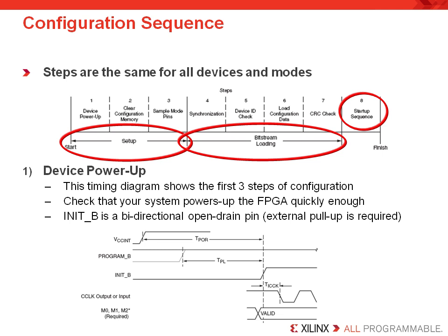As you can see from the diagram, the device has to power up with the VCC internal rising sufficiently. The rise time will vary by device, and we encourage you to review your device documentation to find out your device's particular needs. But this is probably the number one mistake users make: insufficient rise time. If the rise time is insufficient, you can expect the FPGA to never look like it has configured, which means that, of course, the done pin will never go high.